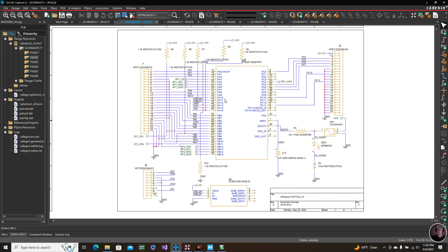There's supposedly internal pull-up resistors on all, or most of, the STM32 series for the F series. This probably helps with your signal just a little bit, just because you're getting a slightly faster response, and you'll probably have less errors here, and this is just helping the communication and the programming. So once again, pull-ups are here, and then your pull-down is here for your custom hardware.